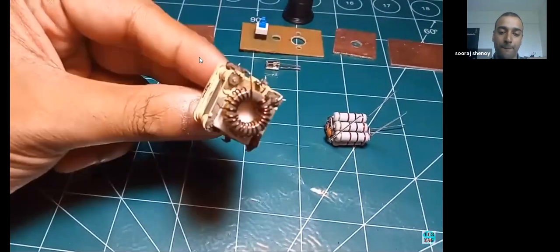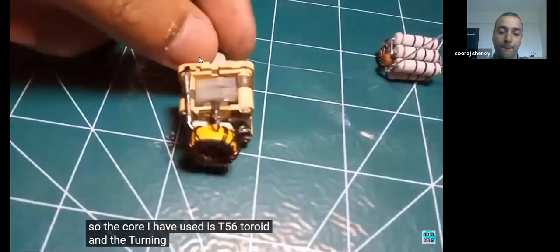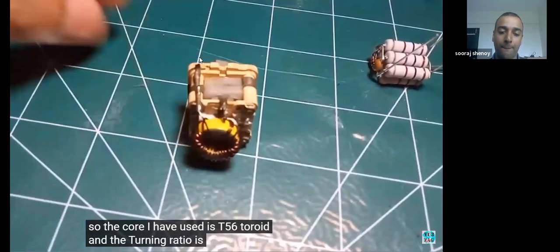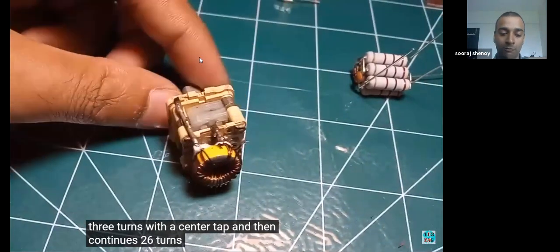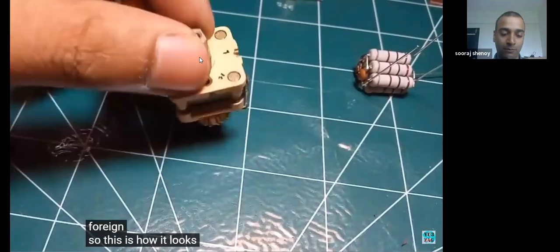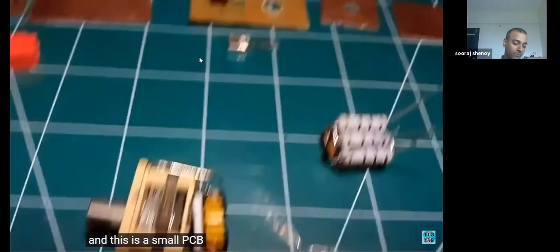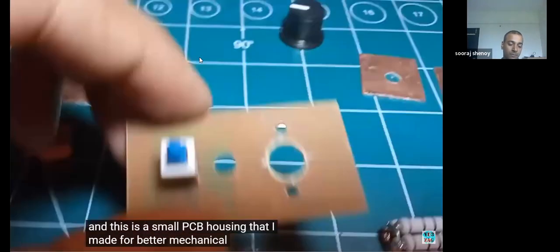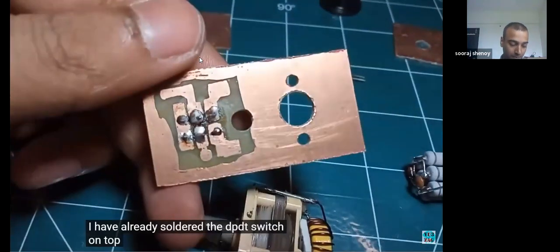The core I have used is a T56 toroid. The turns ratio is continuous 3 turns with a center tap and then continuous 26 turns. So this is how it looks. And this is a small PCB housing that I have made for better mechanical strength, and I have already soldered the DPDT switch on top of it.